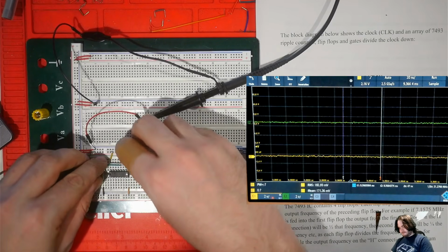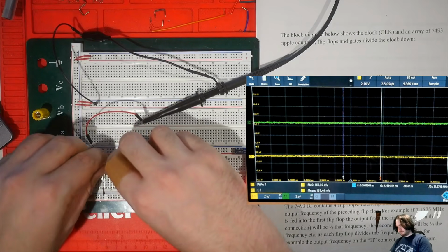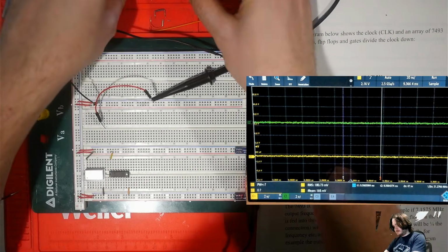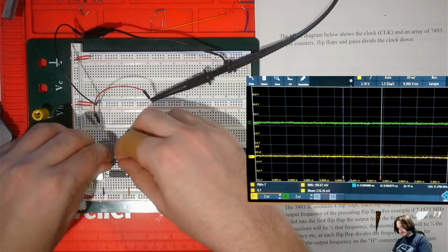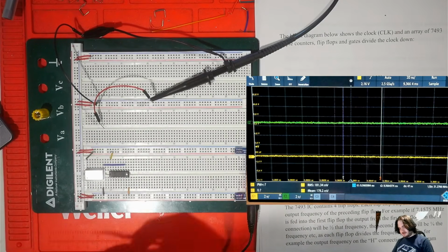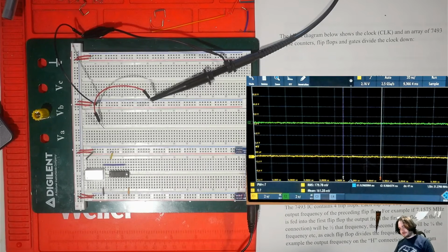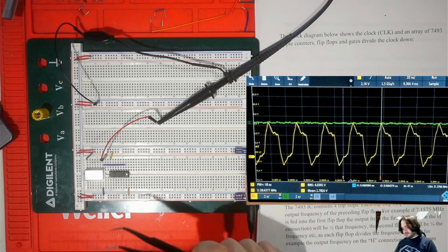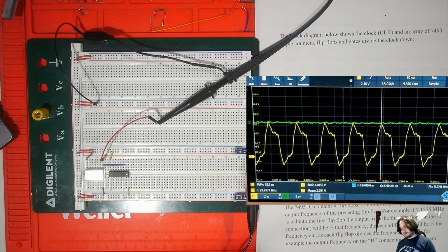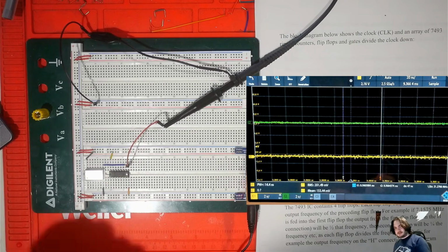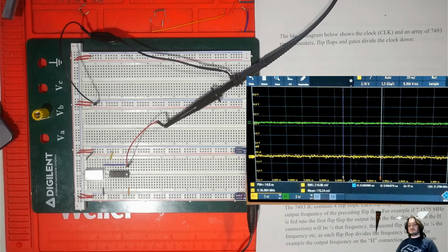So on this chip, on this chip, the second pin from the back on the right side, this guy here is the counter input. Every time a pulse comes through, specifically one of these, every time that goes up, this ticks this count. So we can try putting a pin onto here. It's the lowest bit of the counter, and we find that nothing's happening.